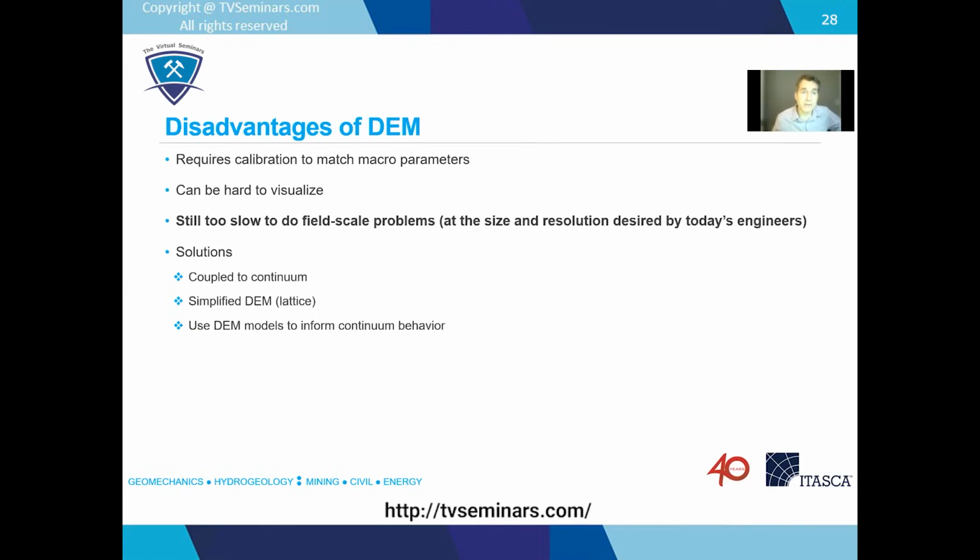Now, the disadvantages of the DEM, these famously require calibration to match the macro parameters. So again, you're dealing with these contact behaviors, and you need to figure out what those contact properties are to give you the macro behavior that you want. It can be hard to visualize if you're used to looking at contours of stress and displacement. It can be a little more challenging to visualize with these particle models.